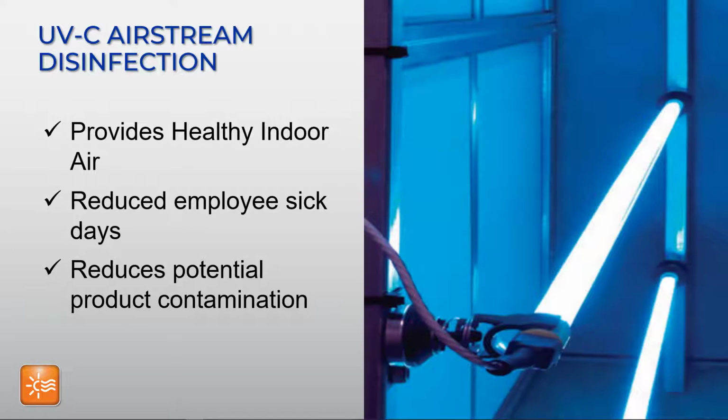With the focus these days on airborne disease, there are some significant benefits to airstream disinfection. The idea is that UVC light is within the airstream, and as air passes through the plenum, the UVC light deactivates microorganisms from reproducing.